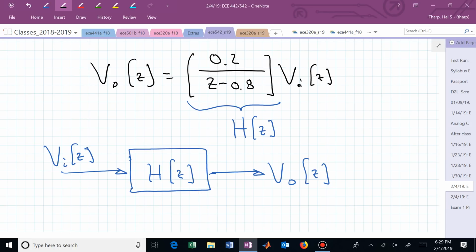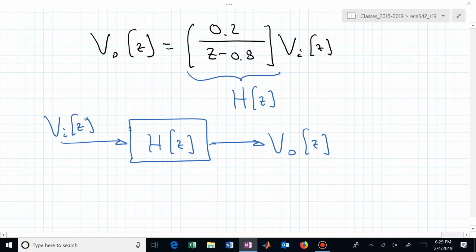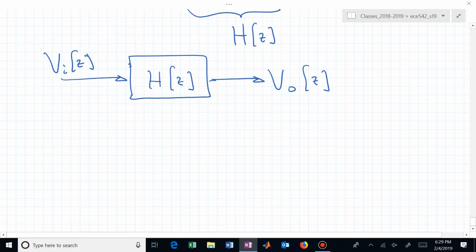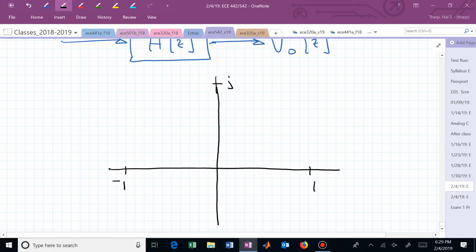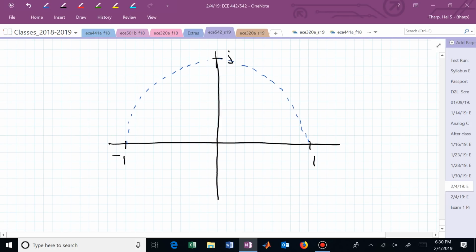If I'm interested in the sinusoidal steady state behavior, maybe what I want to do is look at where my poles are and where my zeros are on this transfer function. I'm sure I didn't give myself enough room vertically. There's j, and now I take out my compass and I make my unit circle, and I didn't want to damage my screen, so you can see that I didn't stick the pin down in the origin very well. But you can on your own piece of paper.